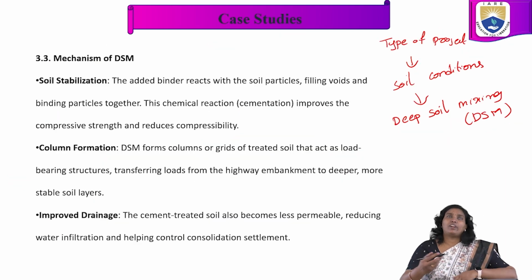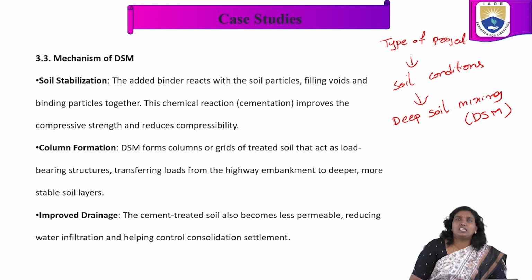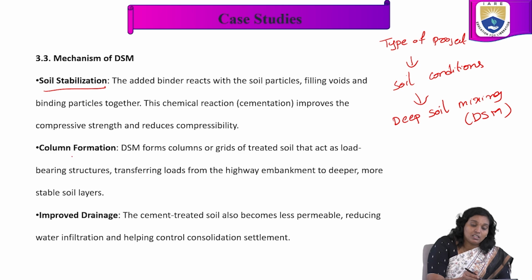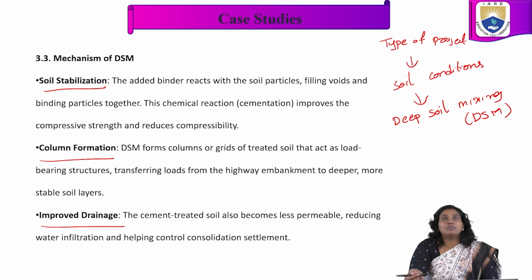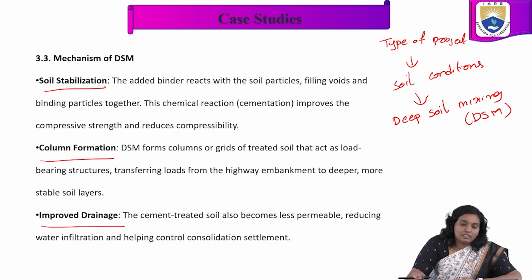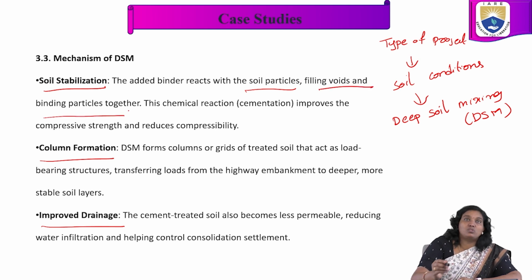In this, different types of mechanisms of deep soil mixing are involved. We will see in this particular slide: soil stabilization, column formation, improved drainage. These are some of the mechanisms involved in this particular technique which we choose. In soil stabilization, the added binder reacts with soil particles, filling voids and binding particles together.